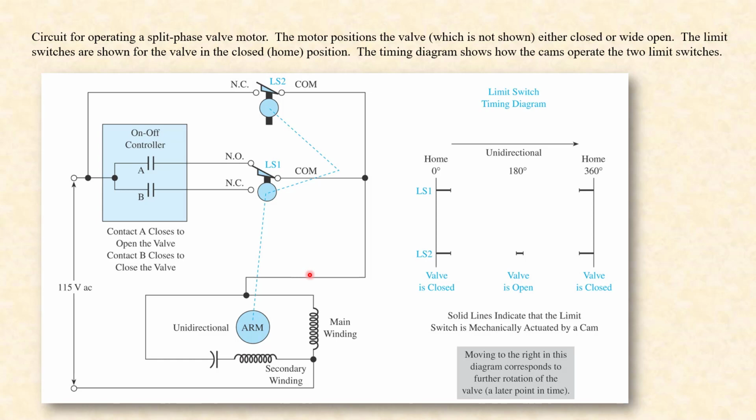The process inputs are telling the controller that we need to close the valve. So as soon as we told it to open, this fell down here and supplied a pathway, but B was open, so nothing happened. But now we're closing B, and I have the power coming in, going through B, and since now this is down here, I'm having the motor turn.